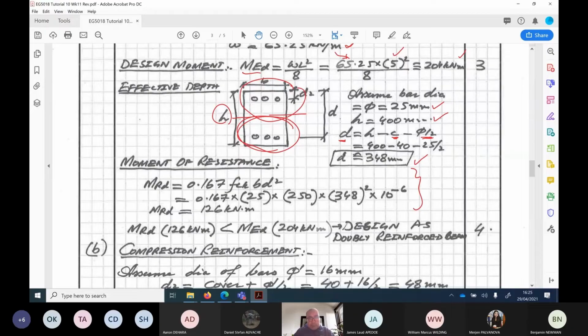But the portion which is below the neutral axis, that is the tension portion. Tension strength of concrete is almost zero. It is 10% of its compressive strength. We ignore the tension capacity of concrete. It means that whatever is below the neutral axis is ignored. Then something should be there to take into account tension. And that's the reason we use reinforcement on the tension side. Did I answer your question?